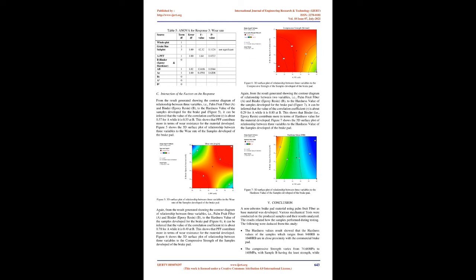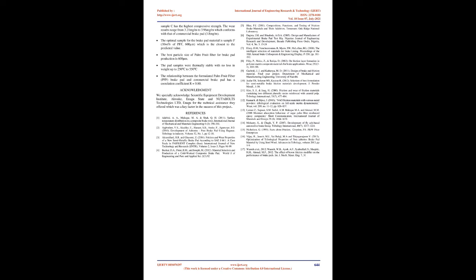From the result generated showing the contour diagram of the relationship between 3 variables, i.e., palm fruit fiber, A, and binder, epoxy resin, B, to the hardness value of the samples developed for the brake pad, Figure 5, it can be inferred that the value of the correlation coefficient, R, is about 0.57 for A while it is 0.53 at B. This shows that PFF contributes more in terms of wear resistance for the material developed. Figure 5 shows the 3D surface plot of the relationship between 3 variables to the wear rate of the samples developed